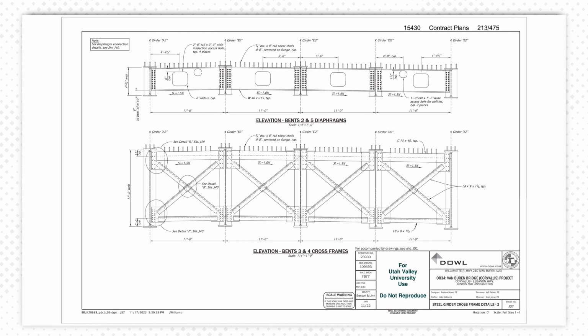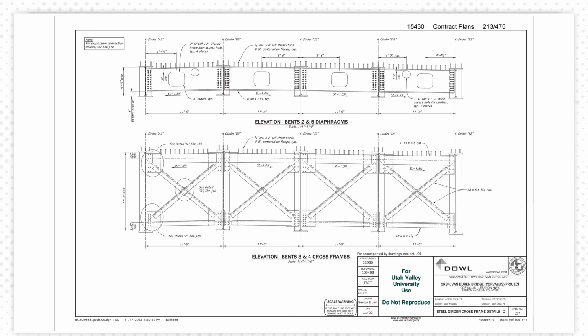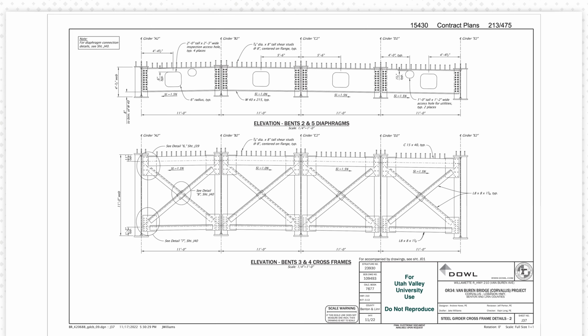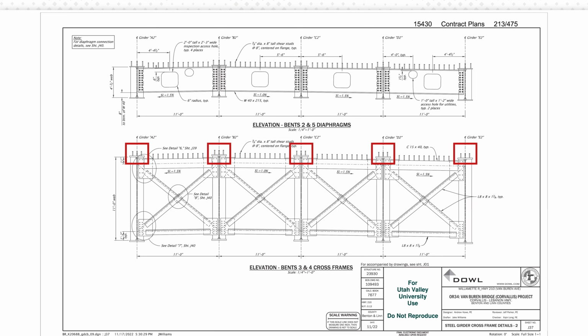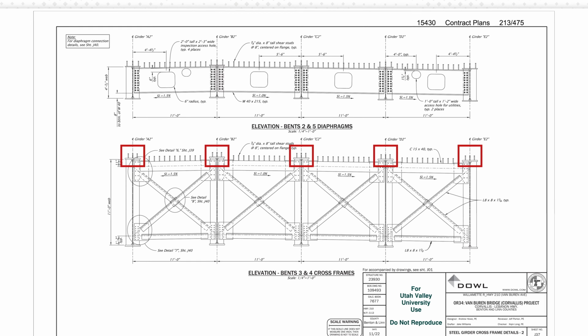So every stage of construction with a girder, it's critical to analyze lateral torsional buckling. And then once it gets in place, it's got to be braced. Lateral torsional buckling is a problem because if it's not braced, you never give the beam a chance to perform as it was designed. Okay, so bracing for lateral torsional buckling: if your top flange is embedded in concrete, that'll be braced. It's not going anywhere.